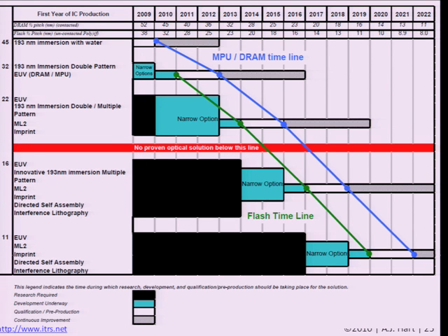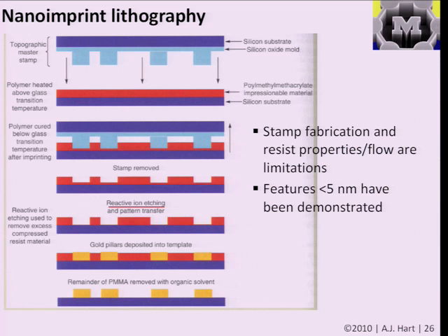Is there a question? For the interference lithography, are they talking X-rays? They can use X-rays, and you can also use beams of light. It depends on the particular process. But then if you have, basically, I don't have that in the lecture, maybe I can show at the beginning last time, you use two beams, and by interference of those beams, you can create very fine patterns. But there is a restriction to the types of patterns. Typically, you can only create lines. You can create kind of like sinusoidal fields using those methods. But that's another way of improving the resolution of lithography.